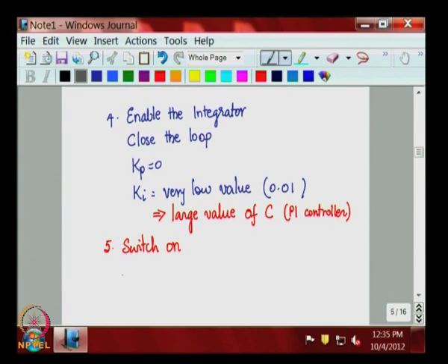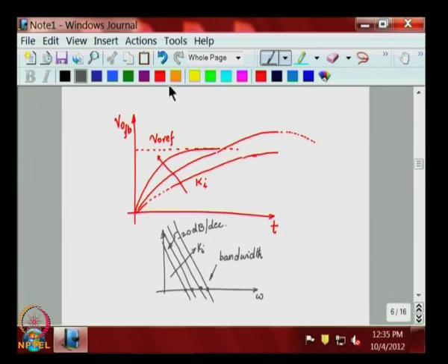Stop the value of Ki, which basically means that you would have chosen one particular value of Ki, the integrator parallel with a particular bandwidth. So, you fix that. So, your low frequency and the steady state portion is fixed, and you know that in the steady state the error is going to be 0, because the DC gain will be infinite.